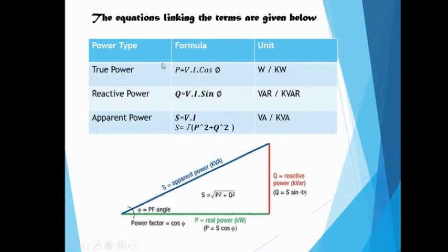Now the apparent power is how much you pay, what you pay for. Real power is what you actually use, and the inductive power is what you need for the machines to run, but you don't really need to pay for it because you're returning that to the supplier. It's reactive. It's not something you use.